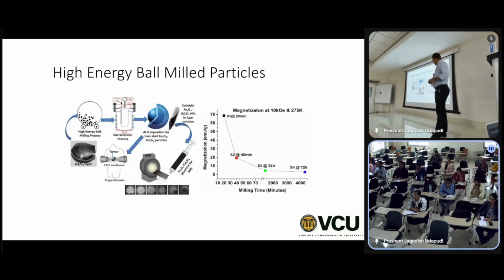So here in this graph, you see that if we take this ingot and keep milling it for a long duration, it completely loses its magnetization. That means it's becoming amorphous. There is no crystallinity. If there is no crystallinity, then some materials lose magnetization, because remember, the magnetization comes from unpaired spins, right? If you don't have the crystal structure, it may not be able to retain that unpaired spin. It may all recombine. The spins might pair with the other unpaired spins and lose magnetism completely.